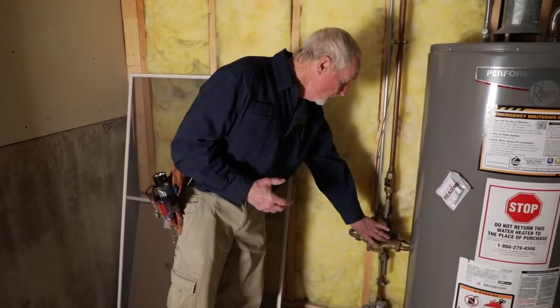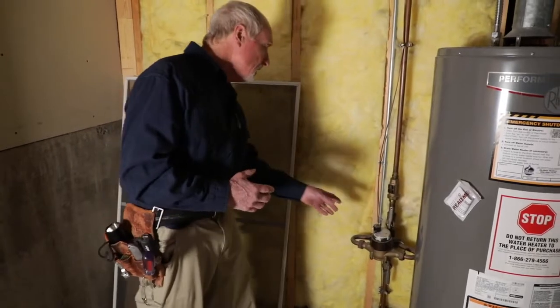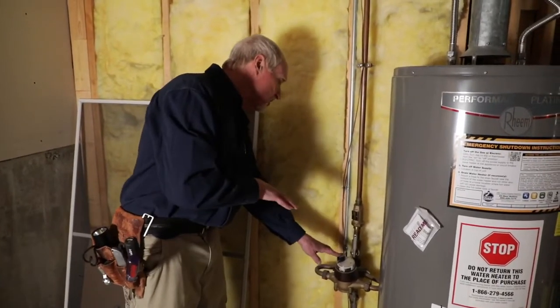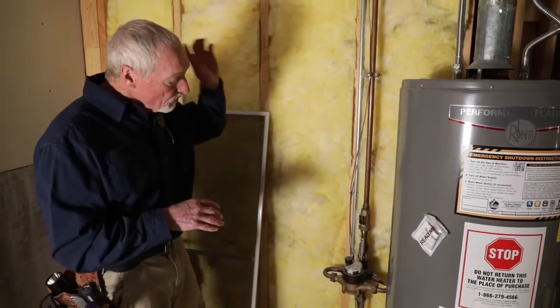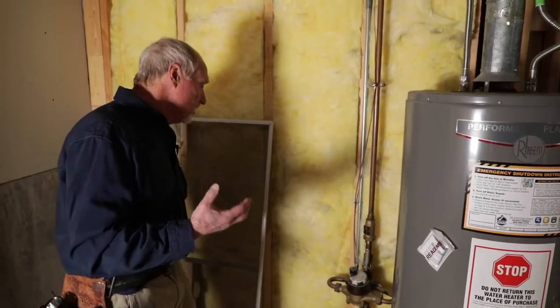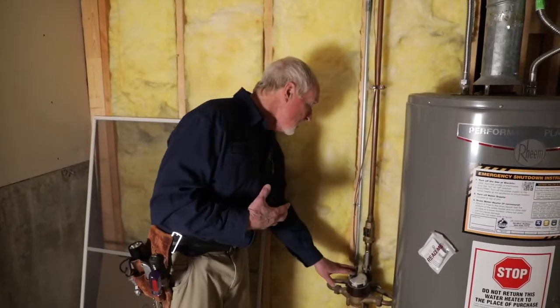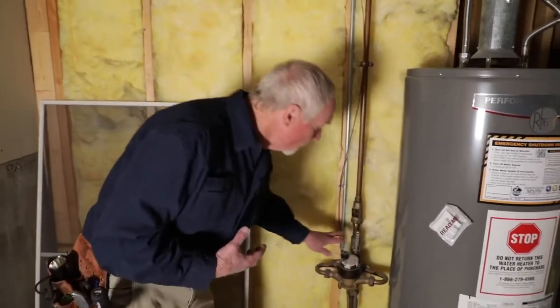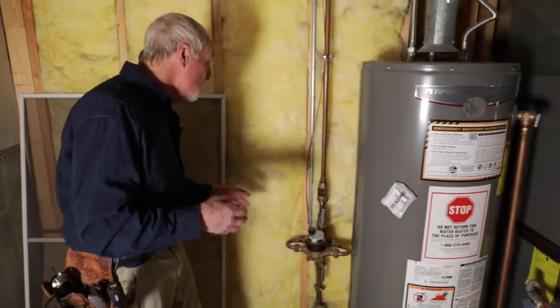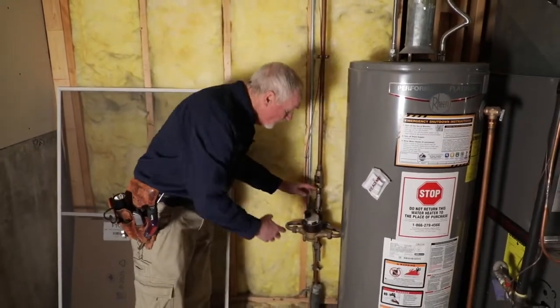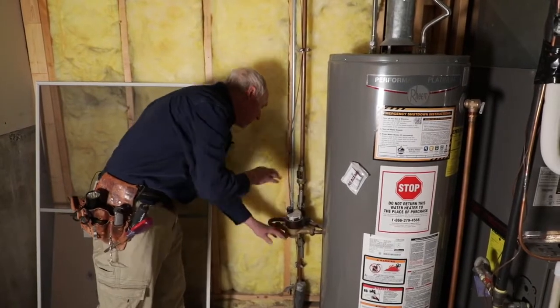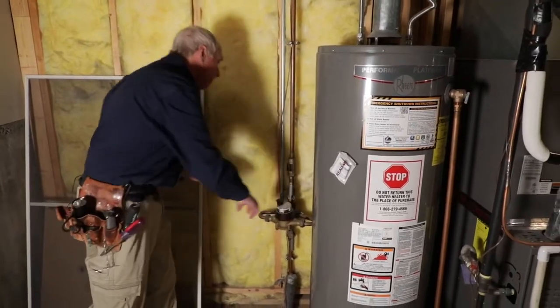And then this is the meter. In this case, and clients will ask you, this sends a signal out to the street so that the city can read the meter without coming inside. And then we have another valve here. Either one of these turn off the whole house. The reason there's two is at the time of construction, they put two valves here so they could isolate the house and the supply coming in to add the meter here.